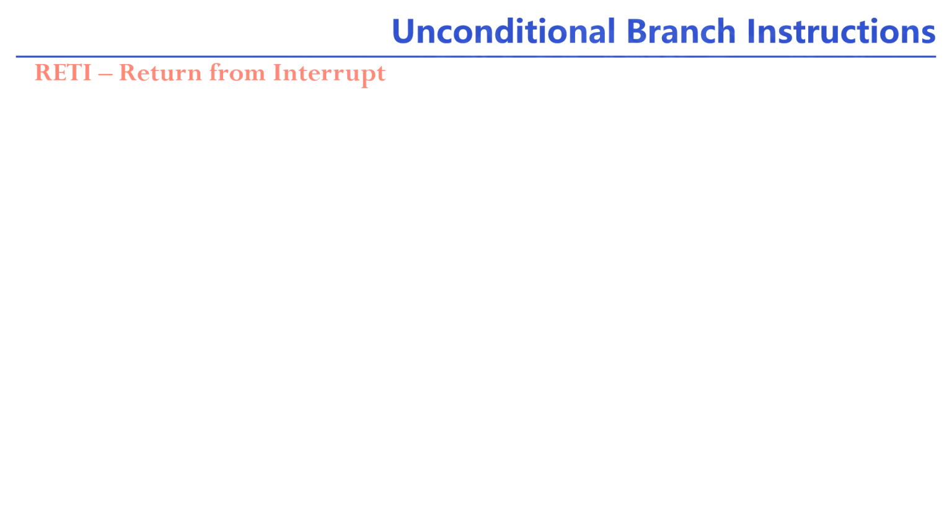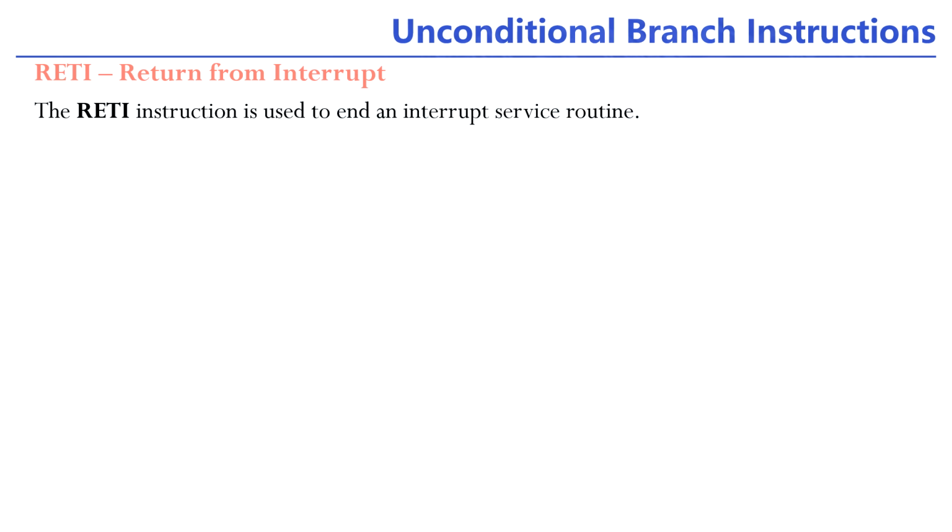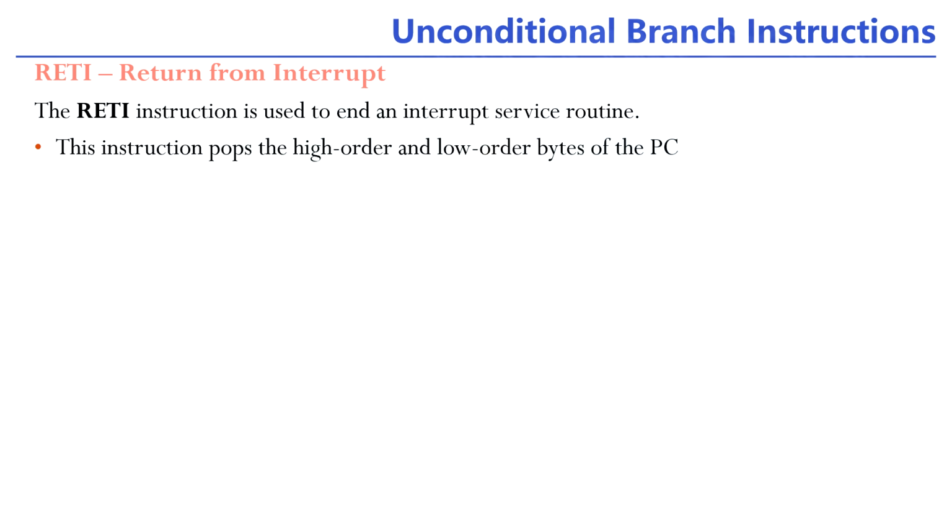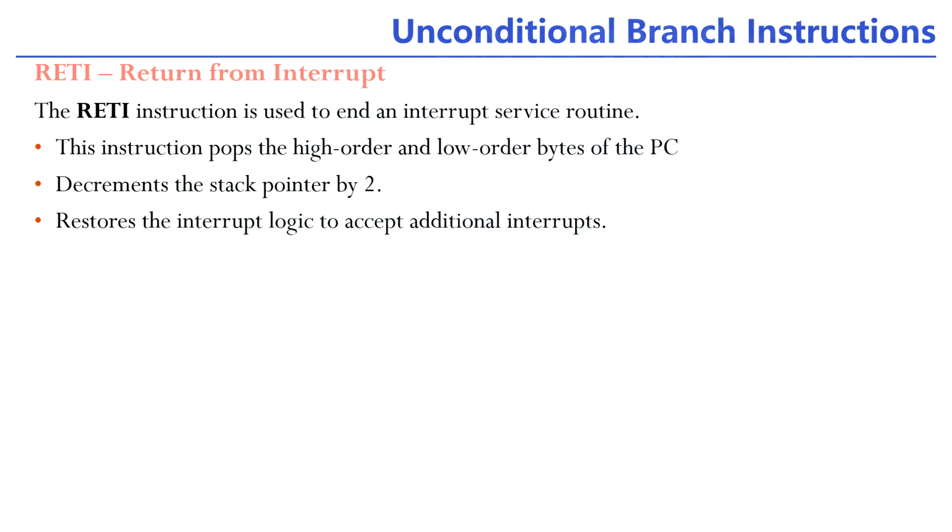Then, RETI. This instruction is used to return from the interrupt. The RETI instruction is used to end an interrupt service routine. The instruction pops higher order and lower order bytes from the PC, just like the RET instruction. It also decrements the stack pointer by 2. In addition, it restores interrupt logic to accept additional interrupts.